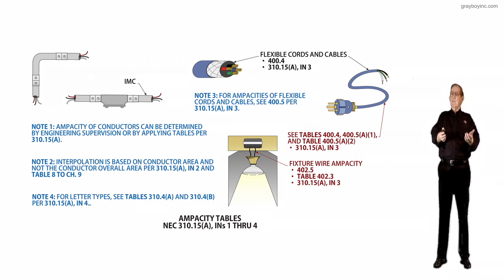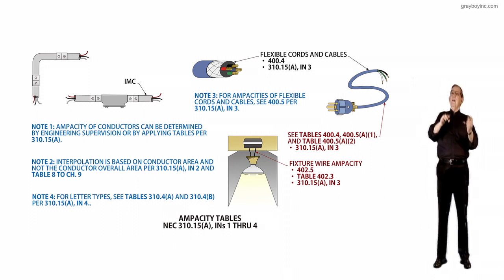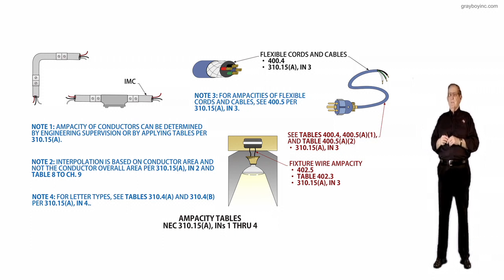And that's where the code talks about these smaller conductors in 240.4(D). And then when you go over to 240.5, you get permission to do all this stuff. And when I say stuff, using smaller conductors to tap into larger conductors protected by larger overcurrent protective devices.